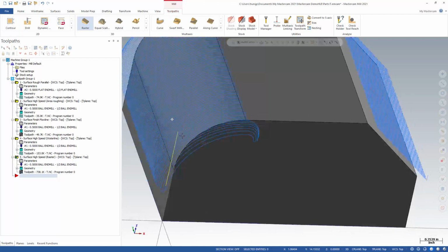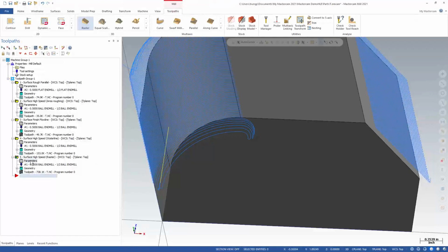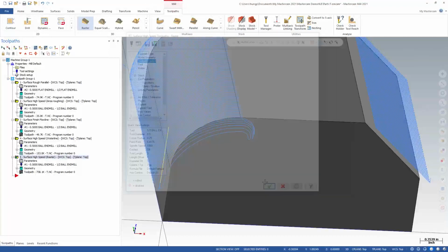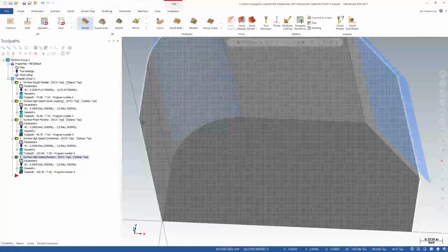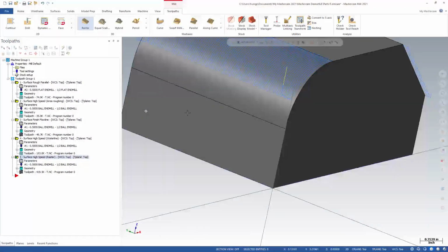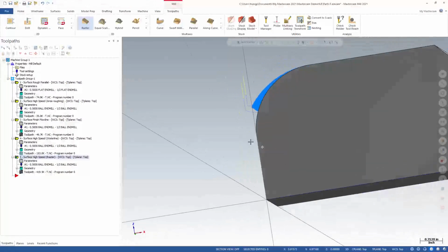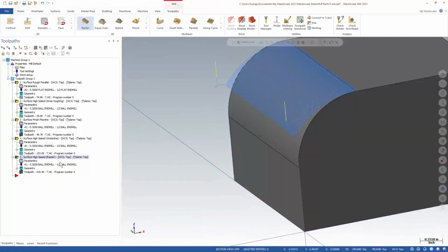You can see it machined the surface, but it will actually cut into the parts. There are a couple ways to fix it. One way, again, is to include this. But if you do that, you chop the toolpath. Anything outside is gone. Anything along this edge up is gone. So it will only cut a certain area.